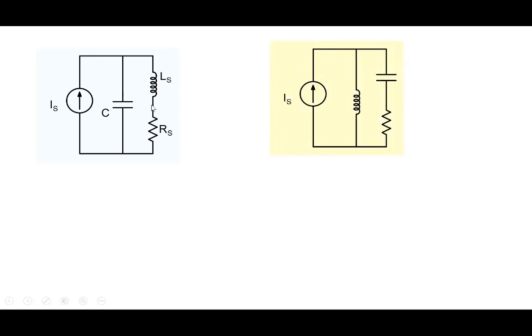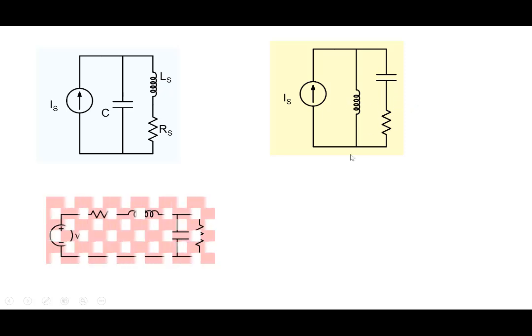So we can also have circuits like this here. We have an L and a C and an R. And again, this does not fall into the results that we have discussed, but the C and R series combination, you can transform it into a CP and an RP in parallel. Using the same approach that we used here, you could use the same approach here also, and thereby transform it into a completely parallel circuit.